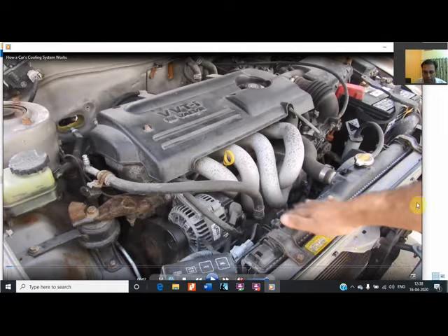because it has to deal with higher temperature and higher quantity of fluid, and this has to deal with the lower quantity of fluid. That is why it is called the evaporator. Both are cooled by the common fan that is placed behind the radiator, because the radiator assembly is important. The fans are placed in this itself. Although the evaporator is placed in front because more cooling is required in it.